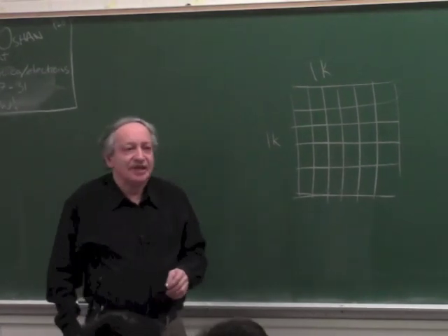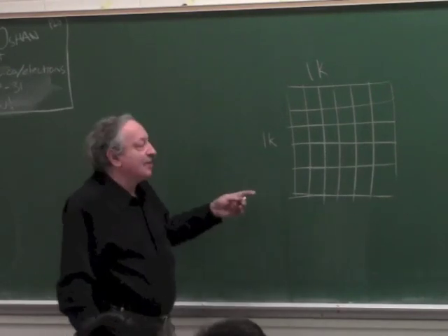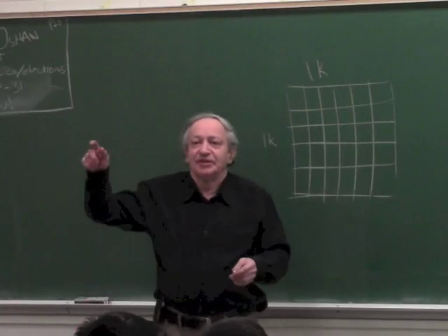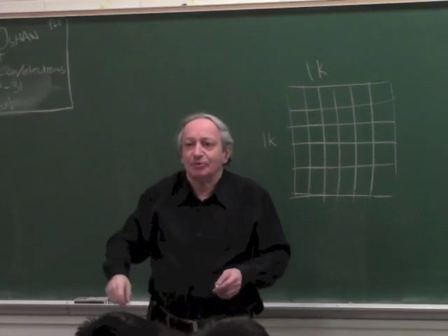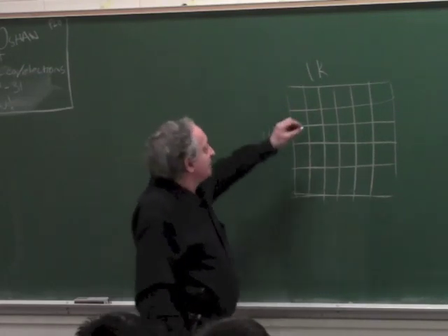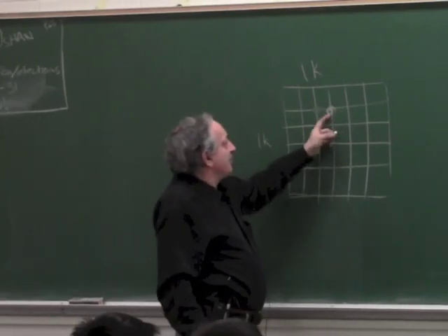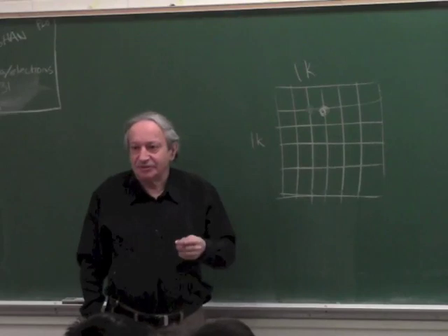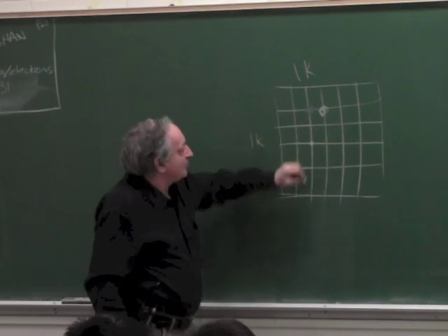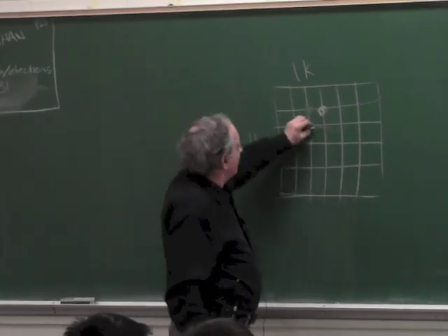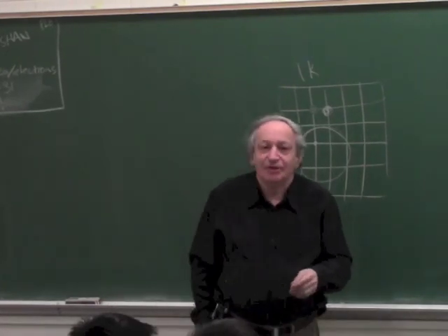Okay, so I want to track a laser pointer on the wall, or a tip on the robot, or a tip of a crane using a camera. So let's say I have a crane, a building crane, which I want to track exactly the tip of the crane to 1 meter. Okay, so I put an LED at the tip of the crane, and then I see the image of the LED here. Okay, and then I track it simply by looking at which row and which column it is, if it's a 2D sensor. So the first question is, should I aim for the smallest, sharpest spot, or maybe it's better to have a bigger spot on the camera, even if it's a bit blurred? So, by now you should know the answer.